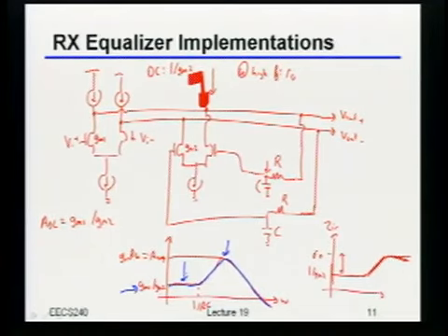Okay. So you said a couple of things there. This resistor here, yeah, it's probably going to add a little bit of noise, but I claim that's actually not that big of a deal. But there's definitely something else that is going to be adding noise. You need to have a lot of gain in the amplifier, so that'll burn power. Which amplifier? The main amplifier.